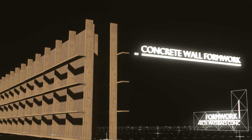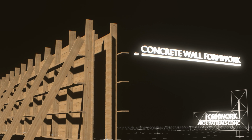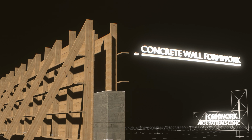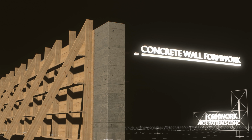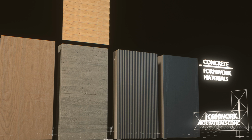Often, this is plywood or stacked wood planks, either way, supported by diagonal braces. The brace is necessary to cover the outward thrust of the liquid concrete as it's poured in from the top and settles into the mold. And this wood construction is why concrete often has the surface texture of wood when seen closely, either a plywood or stacked plank surface accordingly.